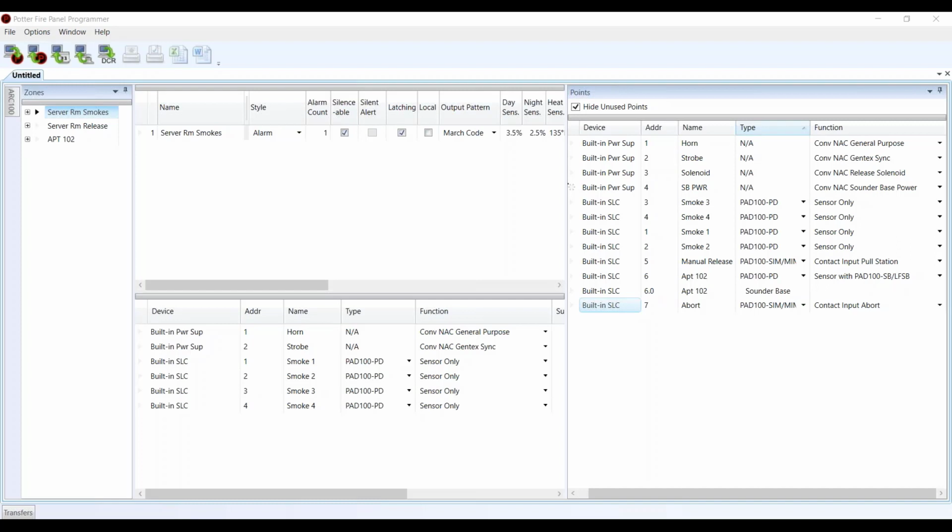When using the low temp function on the heat detector, can you test that without superpowers? That's actually no is the answer. So you'd have to either take an ice pack up there, maybe. Unfortunately, if you don't have superpowers, it's going to be a little harder to test. Some people use a circuit cooler on it to spray it, but you do have to change that temperature on it. No way to do so.